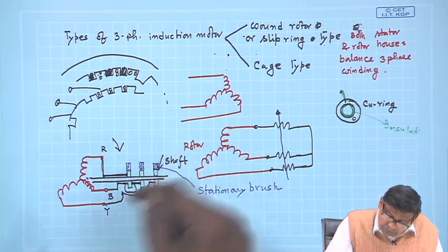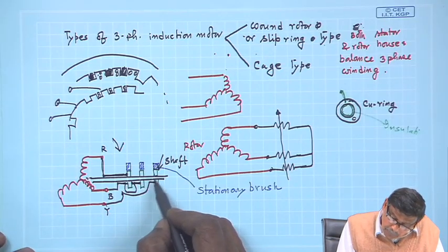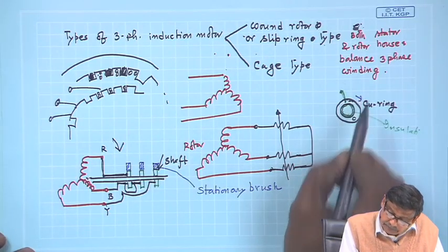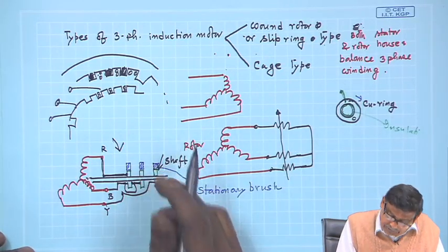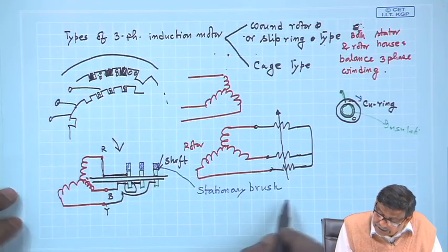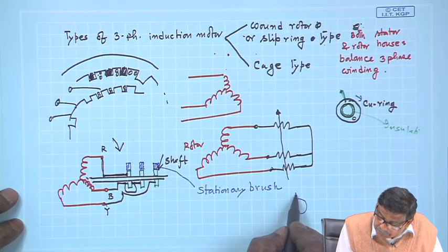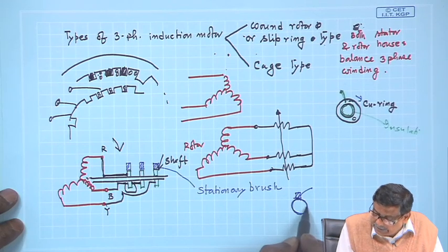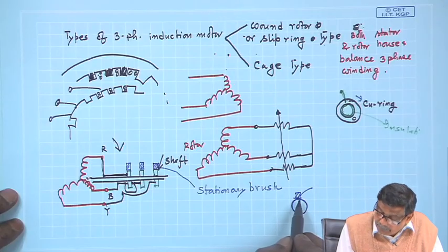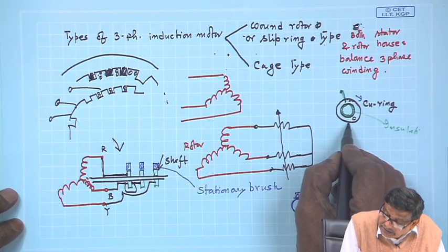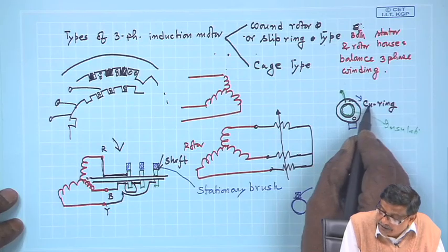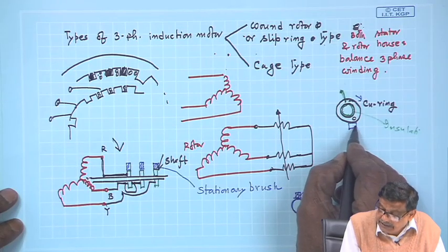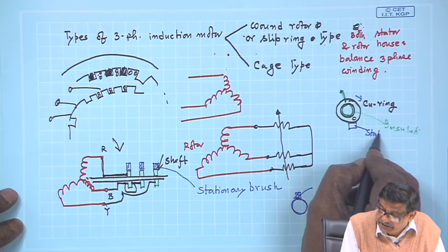As the rotor will rotate, as I told you, this copper ring too will rotate, but let it rotate. I am putting a brush over here, which is fixed. So, no matter where this copper ring is right now, this brush will make contact with every bit of the copper ring as it moves. This is stationary, mind you, stationary.